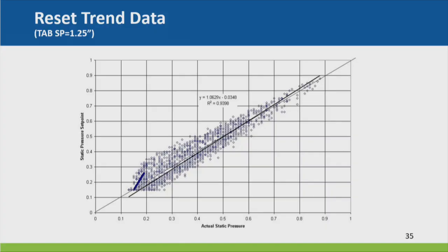By the way, we often use these plots where you put actual versus the set point on top of each other to see if loops are tuned well. And you wouldn't think, like, this doesn't look all that tuned, but it actually is pretty good because you usually tune it way up here, you know, design conditions. And then as you get to less design condition, it doesn't stay in tune as well. But that's okay. I mean, it's reasonably close. We accepted this. It's close enough.